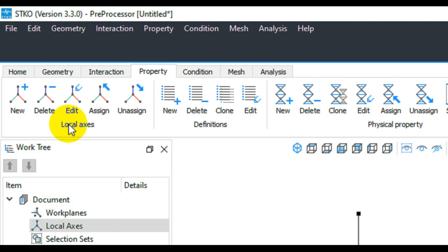If there are inconsistent local axes in your model, that can sometimes lead to discontinuities or errors in the overall solution. To summarize, properly defining and aligning the local axes and local coordinate system for finite element models is critical for ensuring that the FEA model accurately represents the physical system being analyzed, that the loads, boundary conditions, and properties used are accurate, and that the analysis results can be trusted.